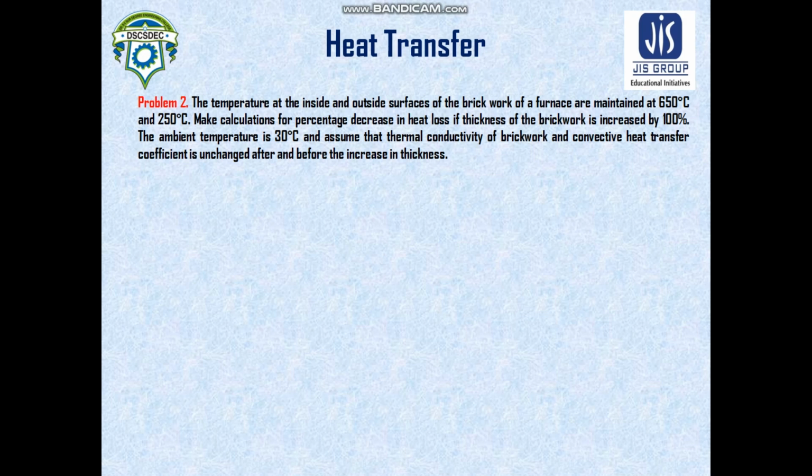The temperature at the inside and outside surfaces of brickwork of a furnace are maintained at 650 degrees Celsius and 250 degrees Celsius. Make calculations for percentage decrease in heat loss if thickness of the brickwork is increased by 100 percent.